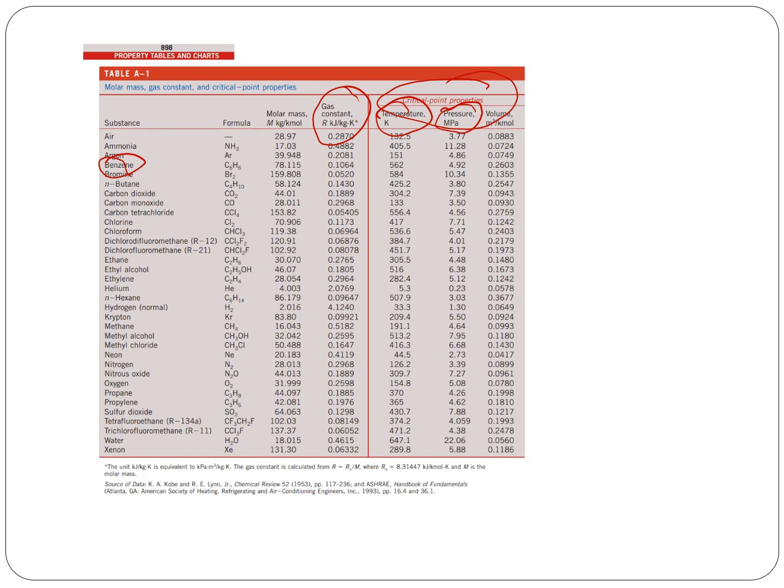Whenever you are trying to find the reduced pressure, P by P critical, make sure both are in the same unit. And for temperature, very important: when you are finding the reduced temperature, it has to always be in the absolute temperature scale.